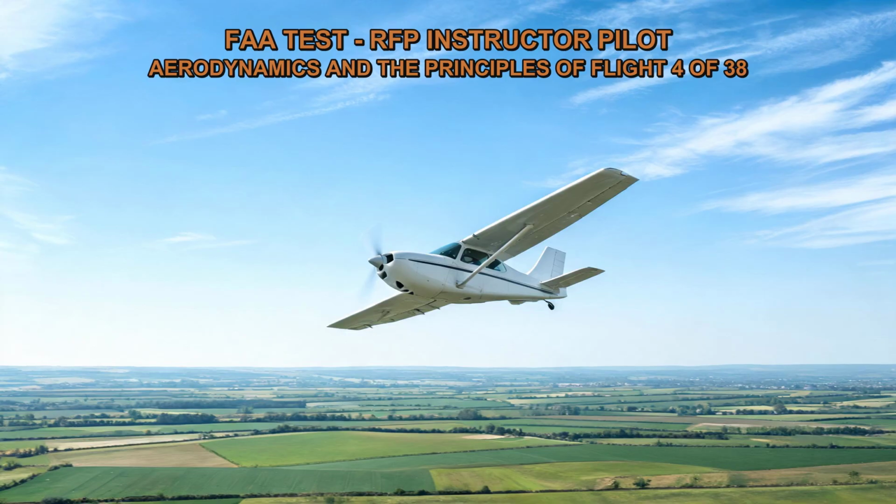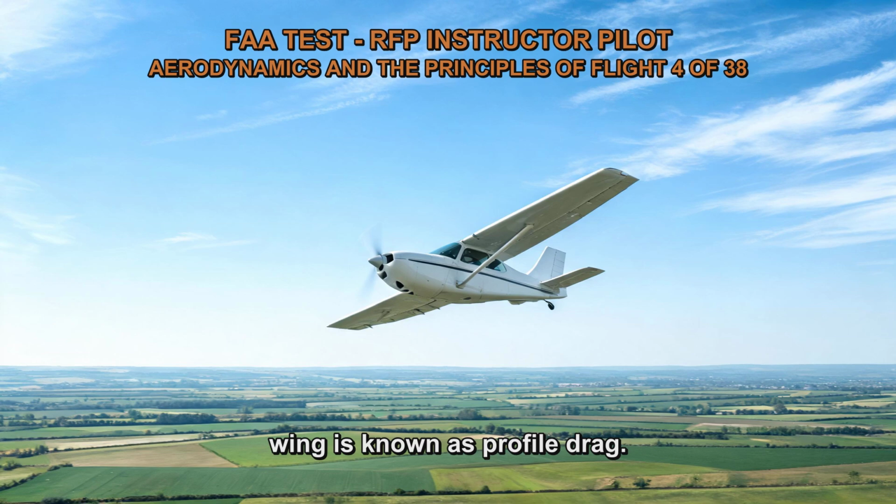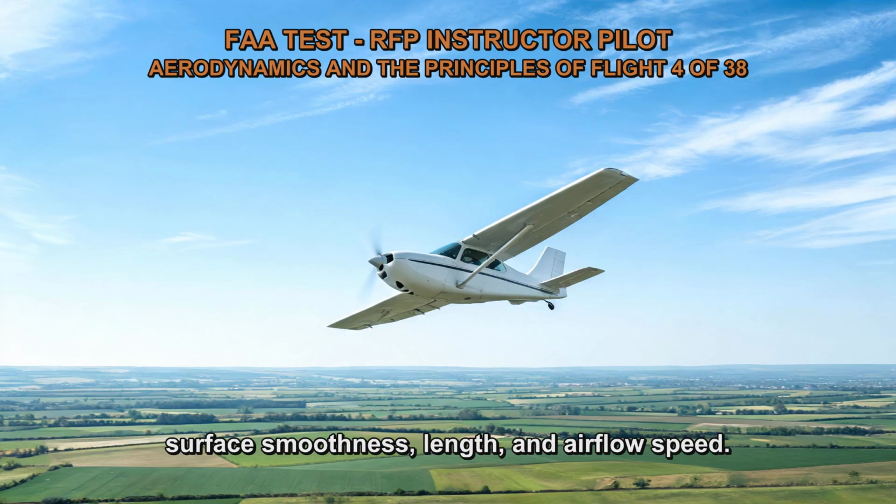will reduce it. In conclusion, the resistance due to the viscosity of the air along the surface of a wing is known as profile drag. It is specifically related to skin friction and is influenced by factors such as wing surface smoothness, length, and airflow speed.